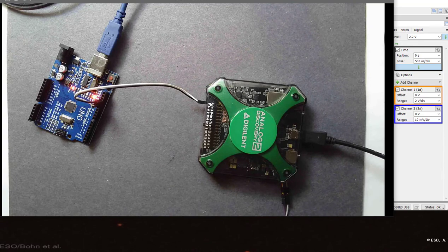Of course, when we short the ends of the inputs to channel 2, we're going to be sensitive to magnetic field coupling. There's very little magnetic field coupling on the board itself or in the amplifier. It's all going to be due to the cables that we see on the outside. And again, it's all about how much coupling there is between the loop of the aggressor that's generating the magnetic fields and the loop of the victim line that's going to be sensitive to the pickup of those changing magnetic fields.